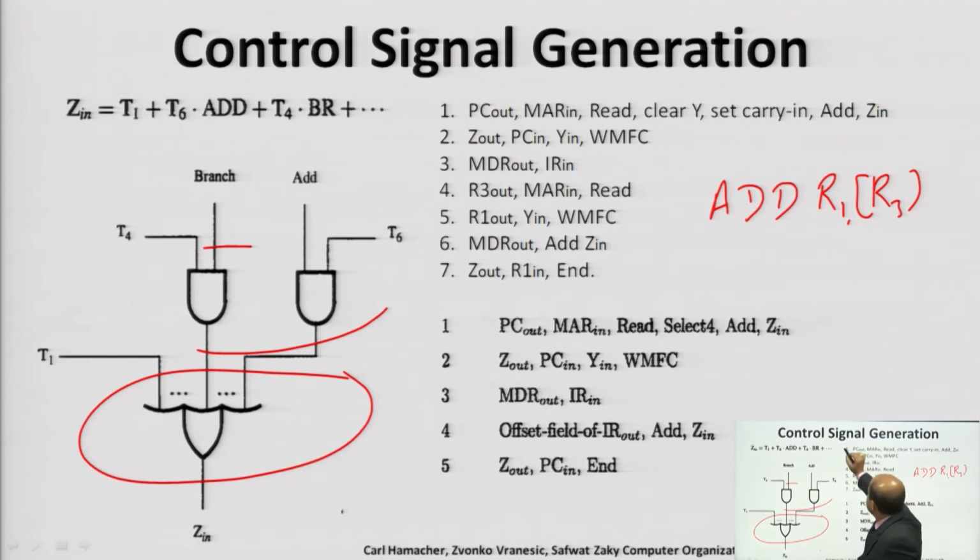This instruction is fetched. So, the first 3 steps are required to fetch the instruction from main memory where this instruction is stored, and this is the operand fetch step, meaning the second operand is given in the memory location whose address is given in R3. So, you can see various commands are generated, or various control signals are issued, by this particular unit. When a particular signal is to be issued, that depends on various inputs.